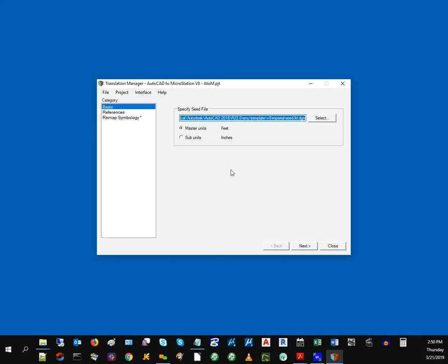And 2 of those 3, when I talked to them and got more details on what they needed to care for on the output side to get the files from MicroStation to AutoCAD form, actually needed settings from the MicroStation translator, going from MicroStation to AutoCAD, where you have the 9 different categories, to handle things like cells.